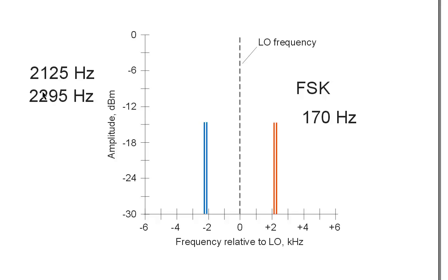The only answer that will provide that state of affairs in this situation is choice A, a few hundred Hertz above or below both the mark and the space frequencies. That's this local oscillator frequency right here. So if we set this local oscillator frequency quite a few hundred Hertz below both the mark and the space frequencies, then we have this state of affairs shown by the pair of red vertical lines for the signal.